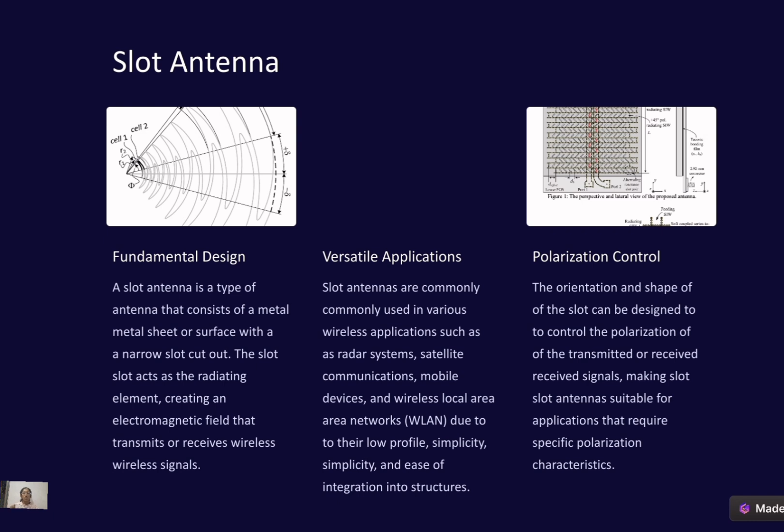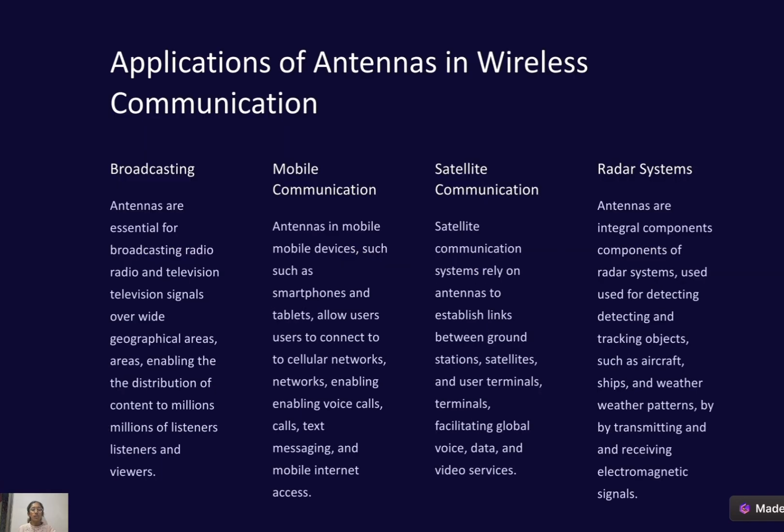And then polarization control: the orientation and shape of a slot can be designed to control the polarization of the transmitted and received signal, making a slot antenna suitable for applications that require specific polarization characteristics. Now, the applications of antennas in communication.